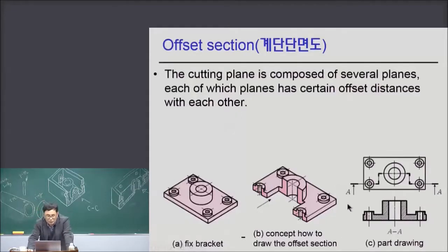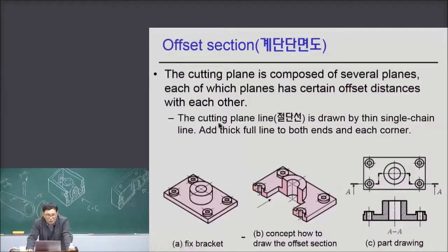But in this case, the cutting plane line is drawn with a thin single chain line, and a thick full line is added to both ends and each corner. Okay, this is the Korean standard of showing the cutting plane line.